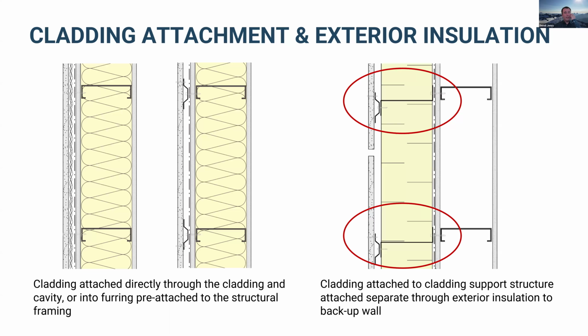So how do we actually do that in a way that doesn't compromise the insulation? The old school approach is shown here, where we just have these continuous metal Z-girts that just punch through the insulation. This actually reduces the effectiveness of that insulation by a huge amount, 50% or sometimes more, depending on the spacing and all that.